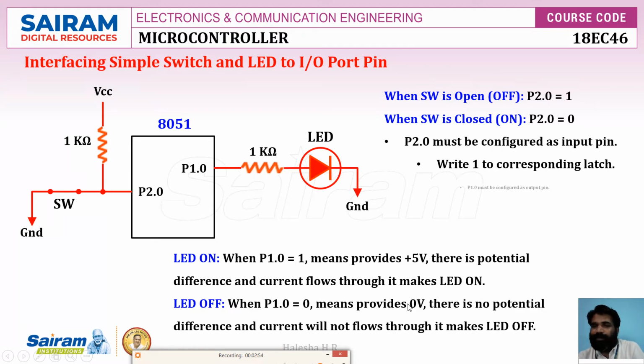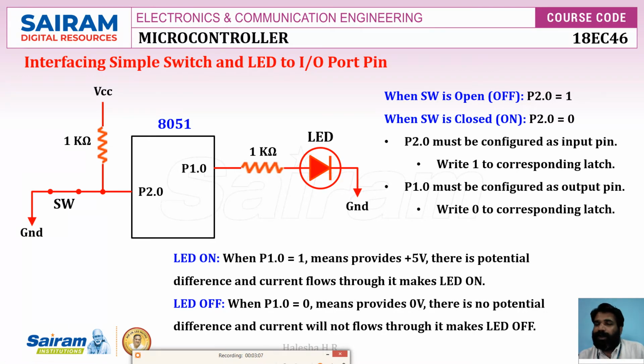So P1.0 must be configured as an output pin, because the microcontroller is giving the value. So it should be configured as an output pin. That means we should write 0 to the corresponding latch. So this is a simple connection.